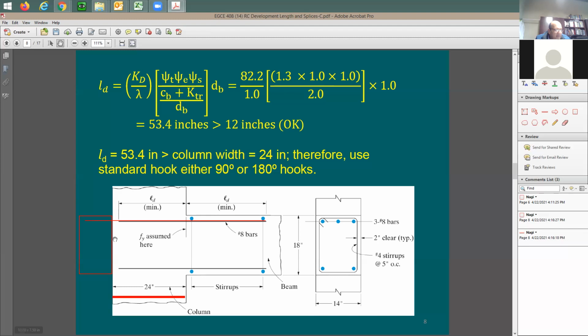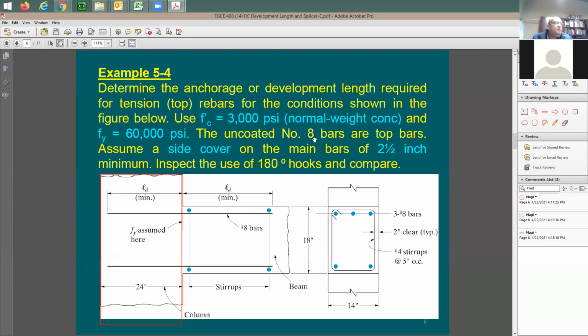Here, the building ends. So you cannot really have this piece be part of the beam and just stick it out, because you need to contain this rebar and put it in some concrete. Not a good idea. So what is the other option? Other option, instead of having this straight development length, we could use a hook. Now let's see what types of hooks are available for us.